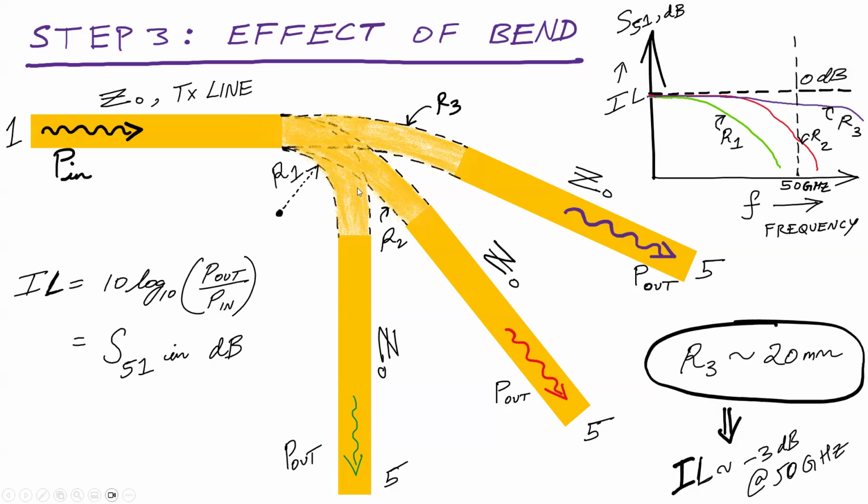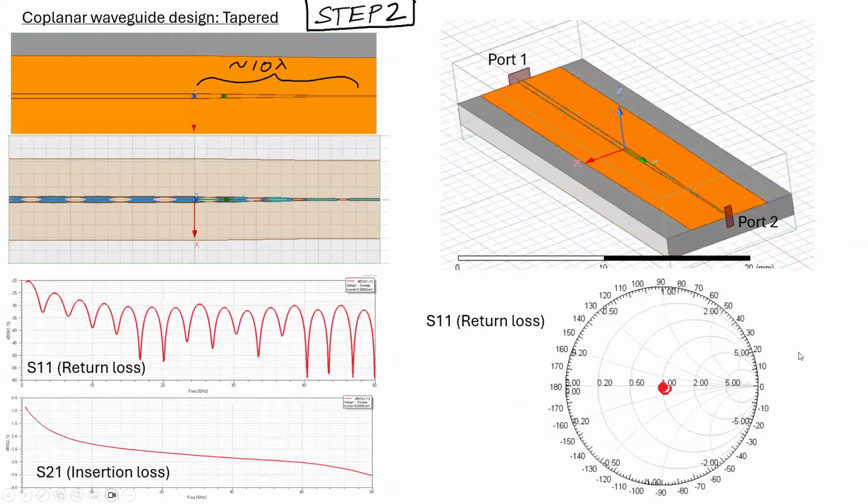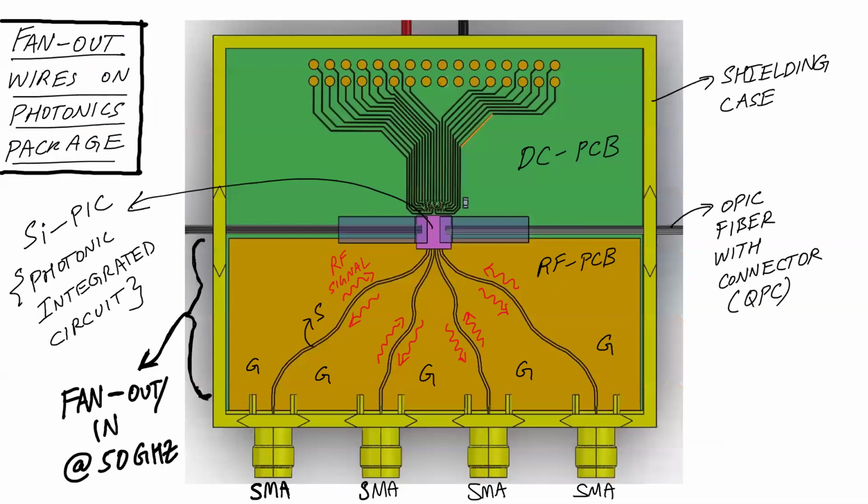So you basically try different radii of curvature and see how the insertion loss is, right? And then I settled on, sorry, 2 centimeter as my target radius of curvature, okay? So then the problem is essentially, I have the taper, so I know what the taper length is.